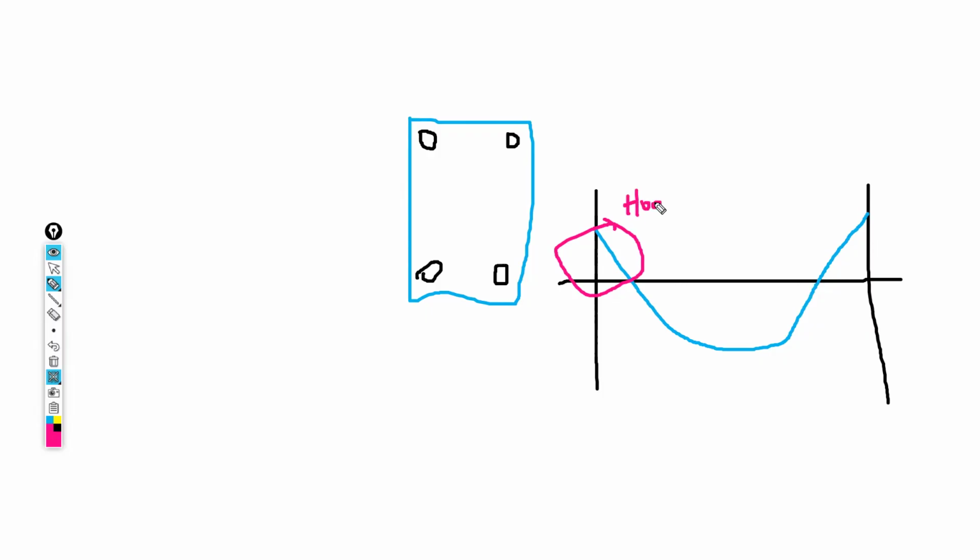So usually when you look at a scenario where you find that you need more bars at the top, that means that it will be along this beam, near the support. That is a section which is cut at this point.